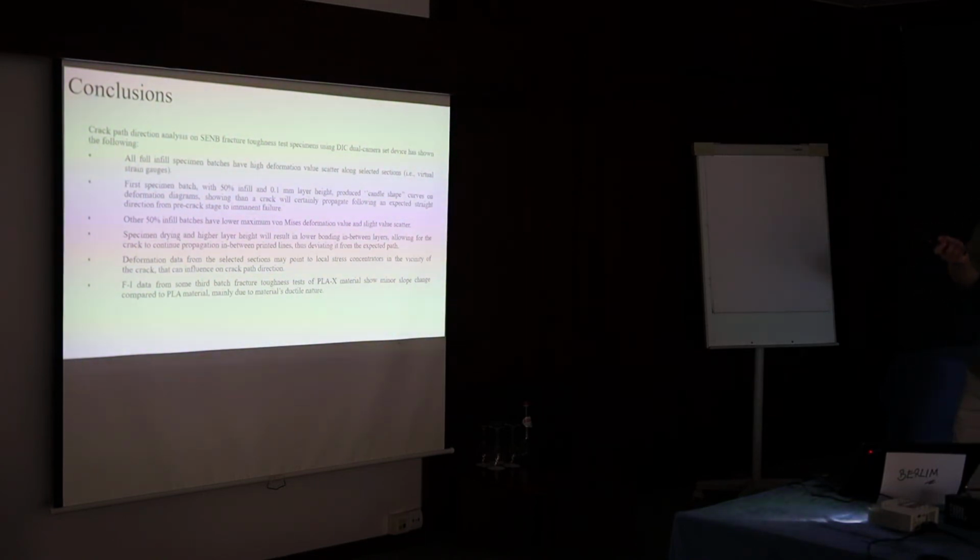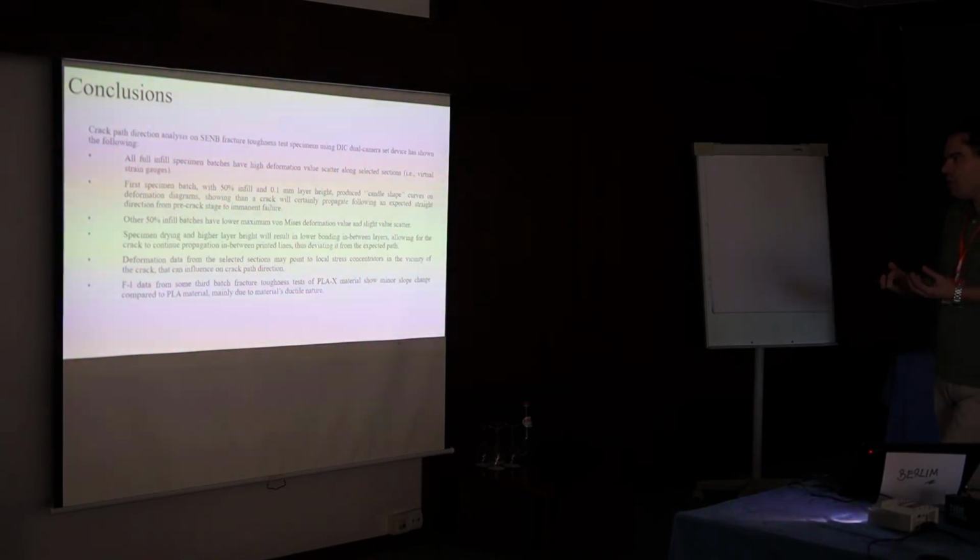We used 5 different batches of PLA and this ductile counterpart, so-called PLAX material, and we concluded that with full infill specimen batches there will be lower deformation values, but higher scatter along selected sections. So we created a few sections on the ligament side of the specimens to capture the deformation values.